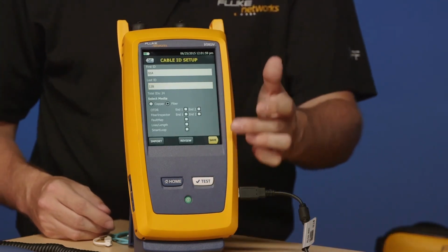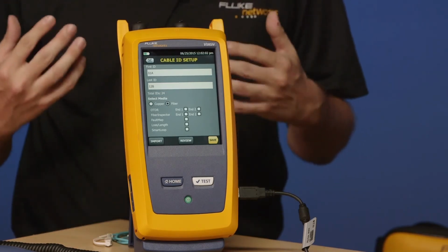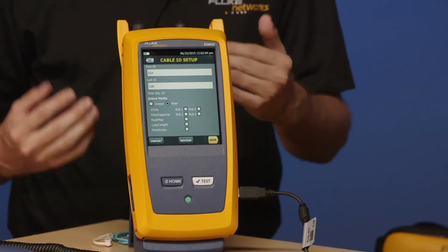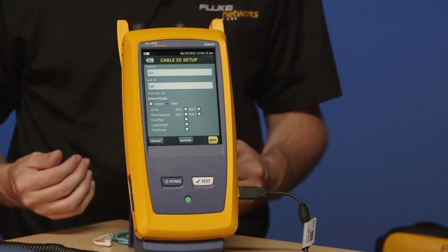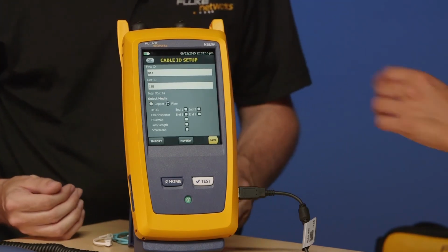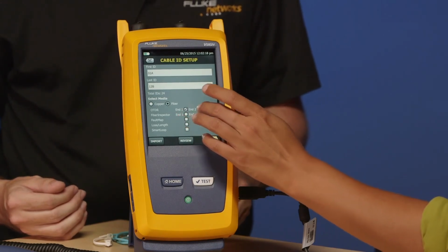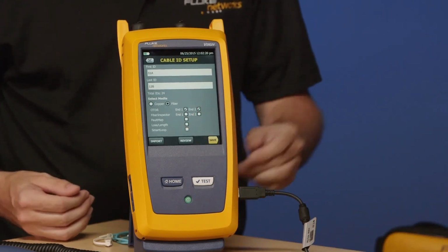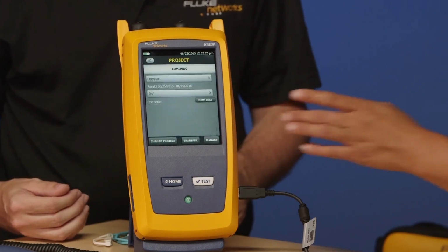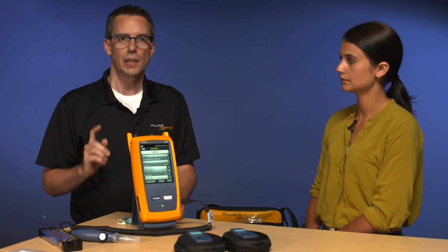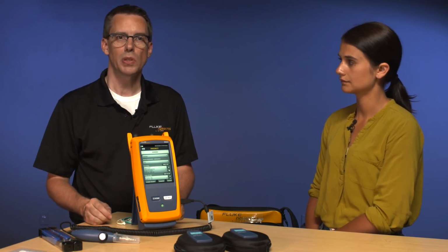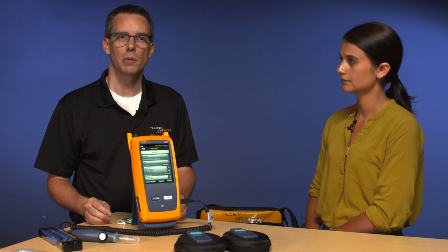Excellent. Now, you'll also see that we get to choose what sort of test we want those assigned to. And we're doing an OTDR test today, and when you look at the OTDR, you'll see it says N1 and N2. We're going to do a fully standards compliant measurement. We are going to be measuring both directions. So go ahead and tap N1 and N2 on the boxes there. And then once we've done that, we'll go ahead and tap save. That's our OTDR setup with our cable IDs and our test limits. In the next video, I'm going to show you how to set a launch compensation and do a successful OTDR measurement.